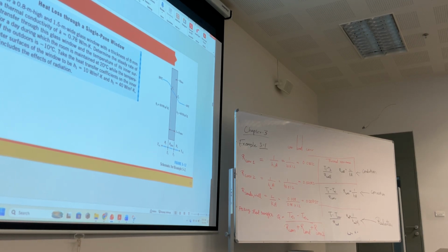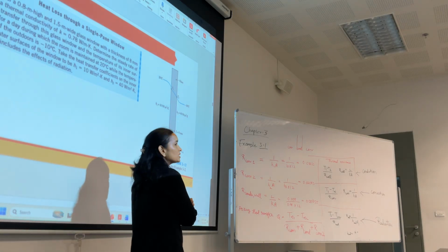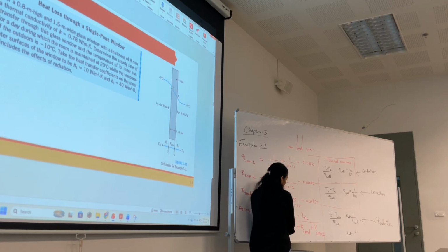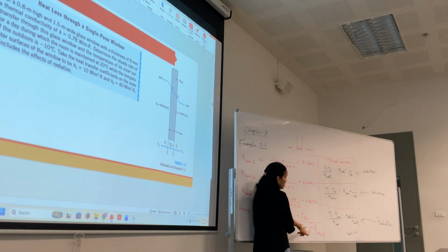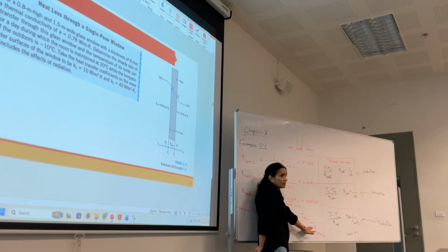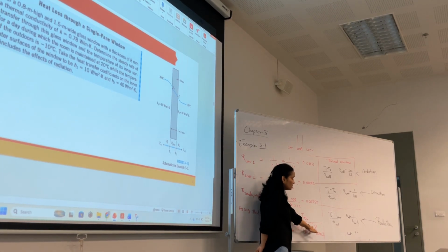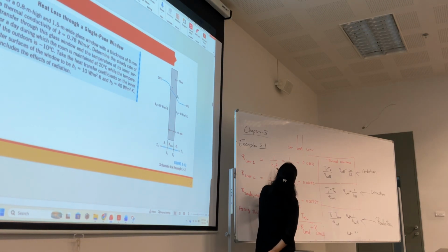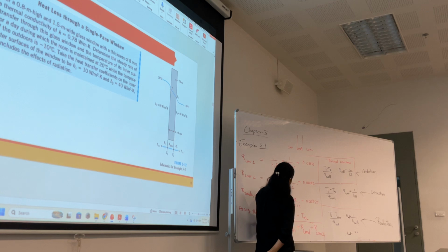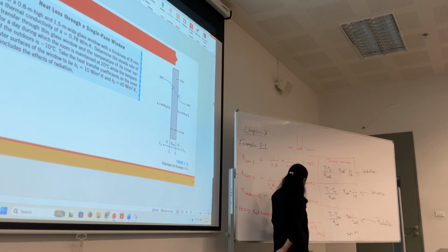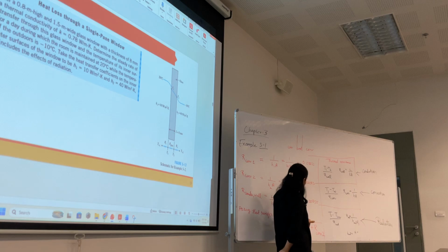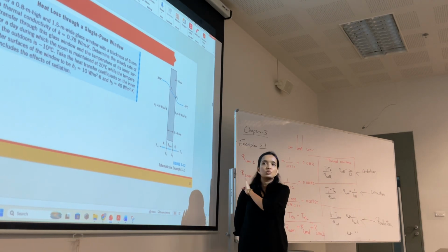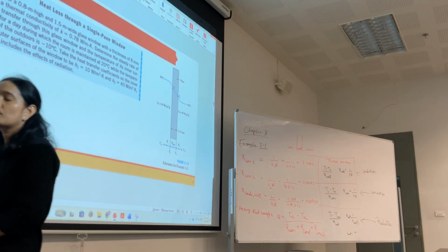So this question is asking for heat transfer through this window, right? We are using the thermal resistance method. So this is the main formula. We are calculating heat transfer Q as T infinity 1 minus T infinity 2 divided by all the resistances: convection, one conduction, second convection. The resistance by convection is 1 over H1A, and then this. So add all of these. You have T1, T2. So put these in and calculate the value of Q. That will be the heat transfer through this window.